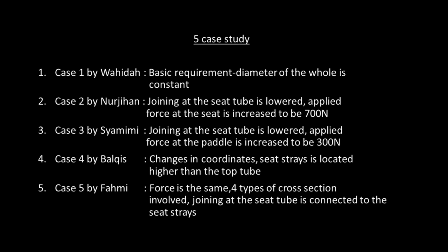The design is a little bit different from the basic structure, where the joining at the seat tube is a bit lower. Then, the magnitude of the applied force at the seat is also increased to 700 Newton. The third case is by Shamimi. The joining at the seat tube is lowered and the applied force at the pedal is increased to 300 Newton.